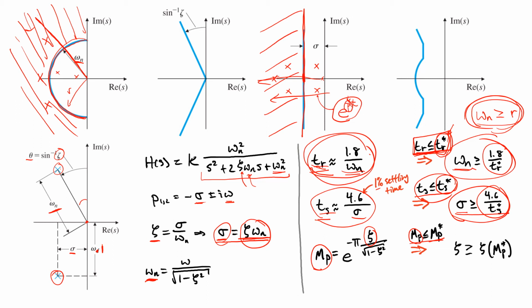What that looks like in our geometric interpretation becomes a little bit trickier in this case, but it's important to remember that for poles that are on the imaginary axis, the zeta value is 0, and for poles that are on the real axis, the zeta value is 1. So zeta just goes from 0 to 1. As you increase zeta from 0 to 1, you move from a direction that's pointing along the imaginary axis directly up to a point that's pointing directly this way.